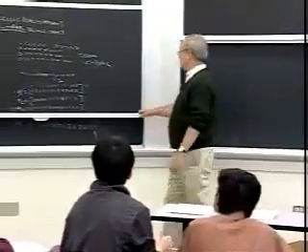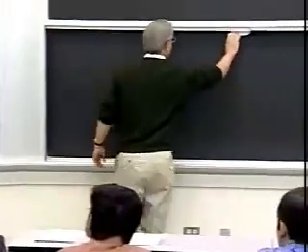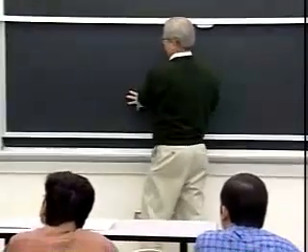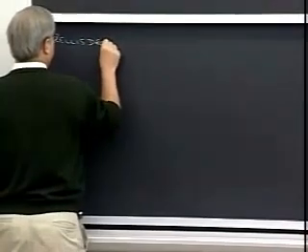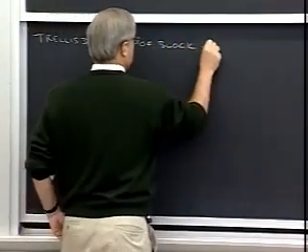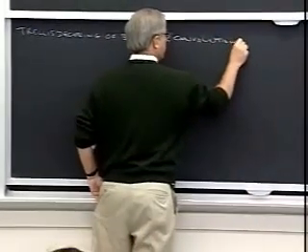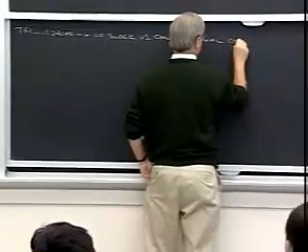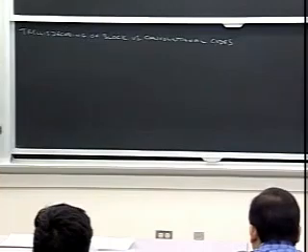The very last thing that I want to mention is we now want to... All right. So through this nice little theory, we've got a way of trellis decoding, maximum likelihood decoding via the Viterbi algorithm of block codes. And now, did we achieve any improvements in terms of performance versus complexity versus the convolutional codes that we looked at previously?